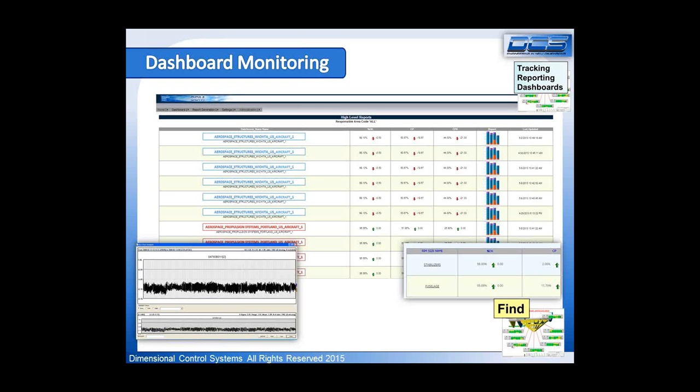So if you think about a tooling supplier, for example, who may be measuring the tool or measuring prototype parts coming off of that tool, being able to have access to that data lets you start to build up a data set that helps you understand the real-world elements and realities of what's occurring in things like springback out of a die, flex of a skin coming off of a tool, or a stretch condition that might be coming off of a tool.